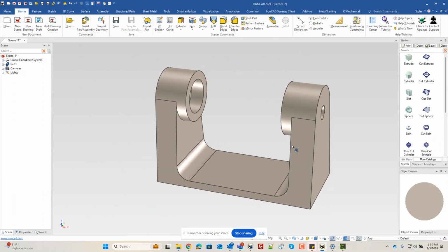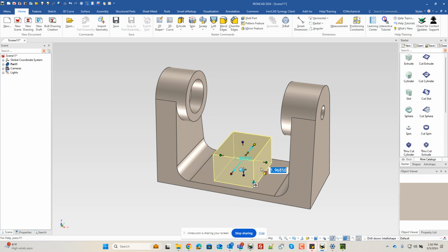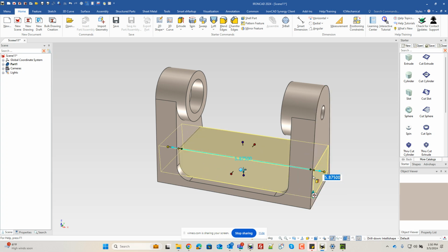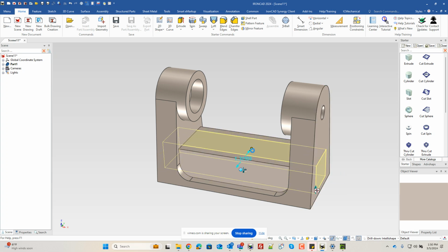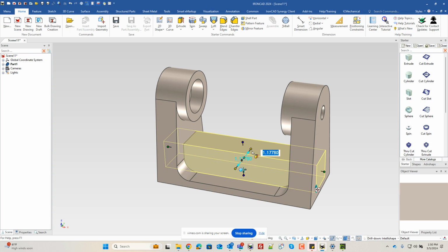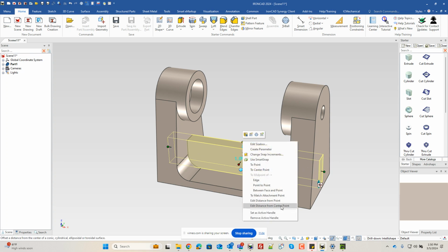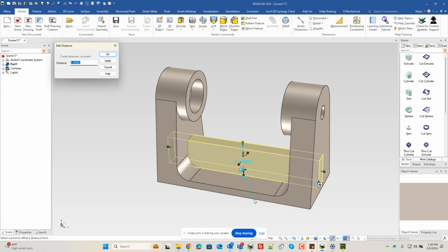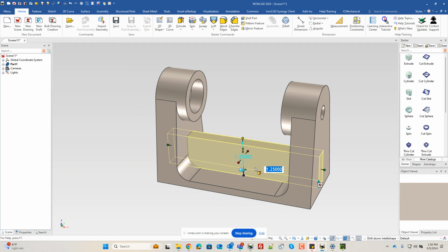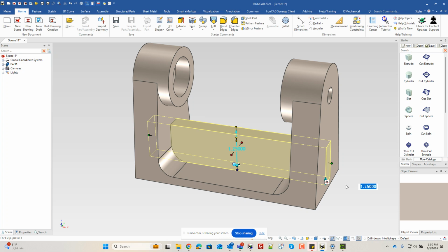And in this case, I'm just going to drop an extrude on here to do this. It's fairly simple. So we just drop an extrude on here. And in this case, we can just right click, snap this to the outside because it doesn't matter. And we know that the base width of this is 0.5 on that. And we know the top of this guy has an edit distance from point, which is our bottom here. It's got a top value on that of 1.5.